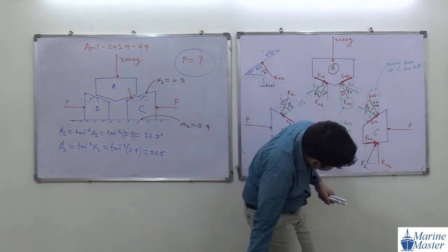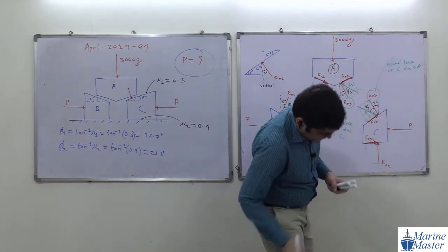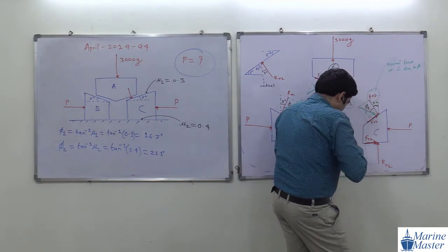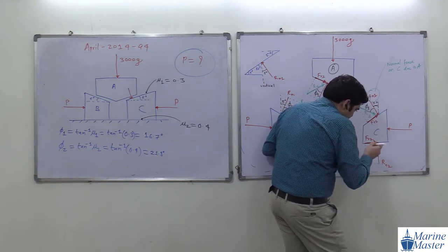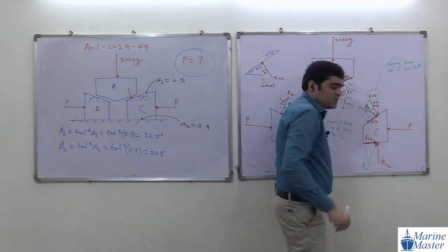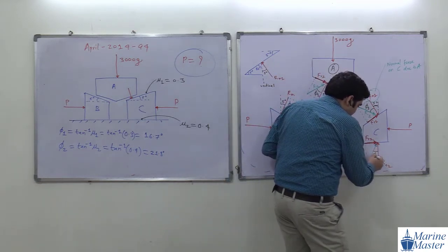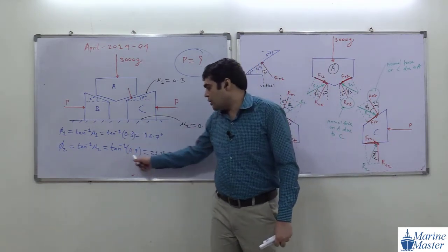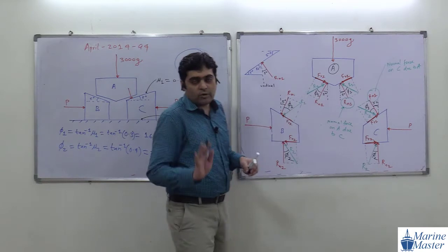Okay. I will use for standard practice same color pen. See the point here, everyone. Guys, see the scenario here. So this will be our resultant reaction R2, and this angle of R2 is phi2. And why is it phi2? Because here we assumed coefficient of friction mu2 and corresponding to mu2 angle of friction is phi2. Okay. So that's why here R2 and Rn2 angle is phi2. Okay. Guys, any doubt in this discussion?